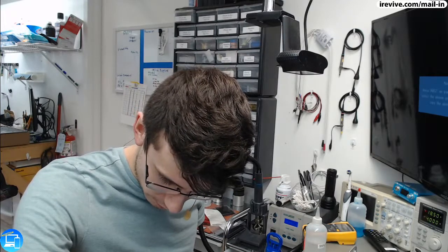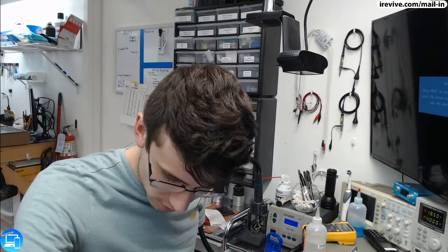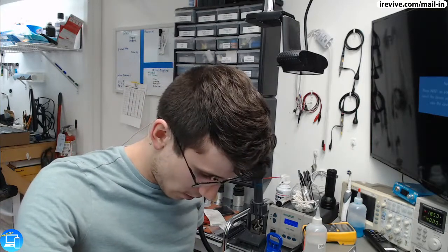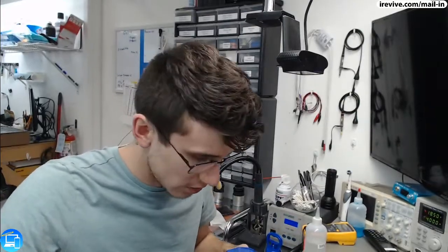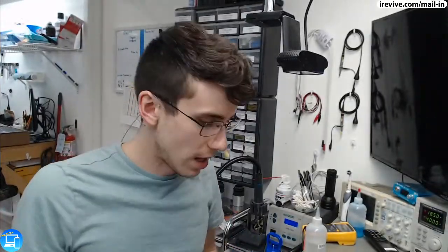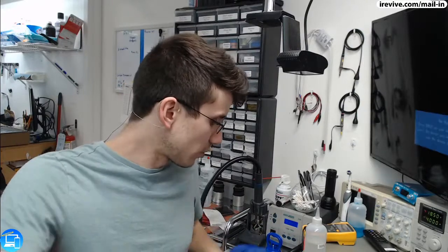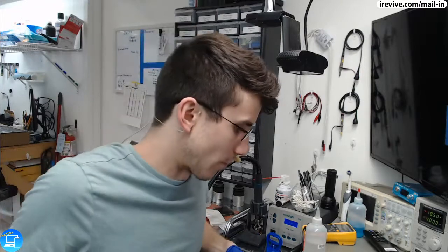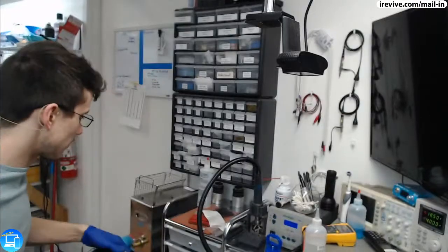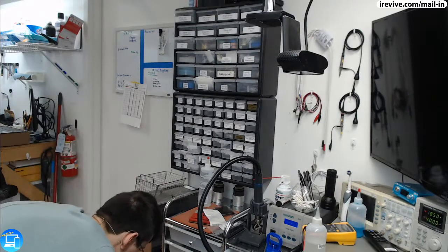So we ended up replacing the CD3211 as well as running a jumper wire on a trace that was completely missing, which fixed the Thunderbolt issue as well as fixed the computer from not turning on. And now Thunderbolt is working, computer is turning on. Got to finish doing a QC. We'll give this one an ultrasonic cleaning probably in the morning because I want to work on another board. So that was a successful board repair. Let's go ahead and work on another one we have here.